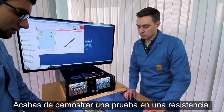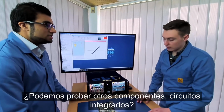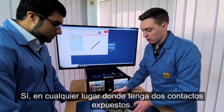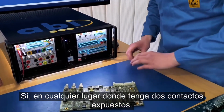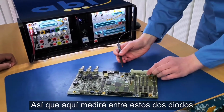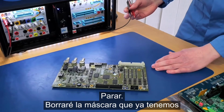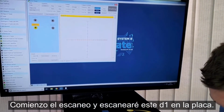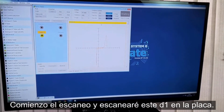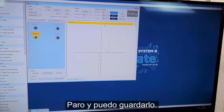Absolutely. You just demonstrated a test on a resistor. Can we test other components, ICs? Yeah, so anywhere that you have two exposed contacts, you need that circuit, or else you get that open circuit. So here I'll measure between these two diodes. Right. I'll clear the mask we've got already. Sure. Start the scan, and I'll scan across this D1 on our board. And stop that one. There we go.